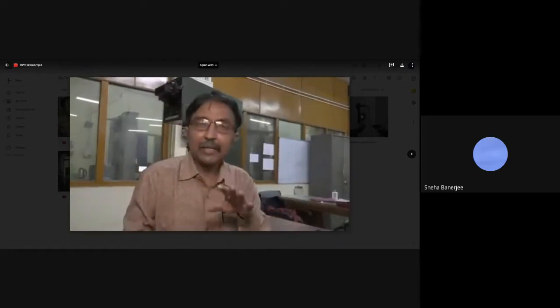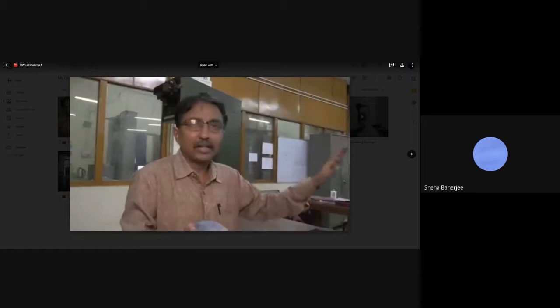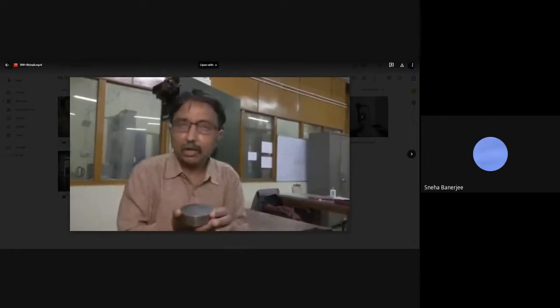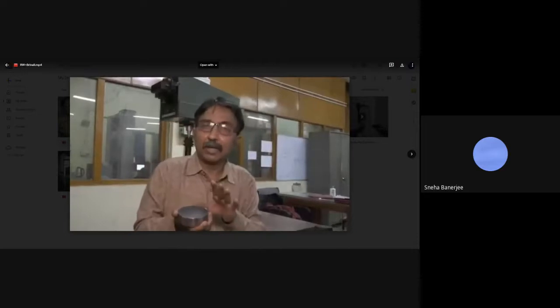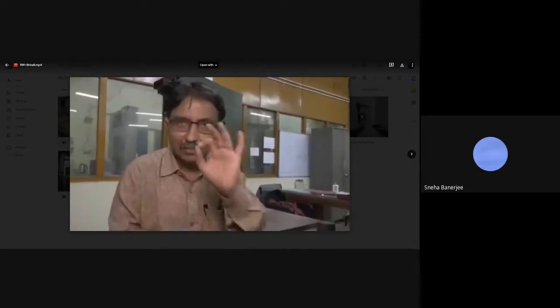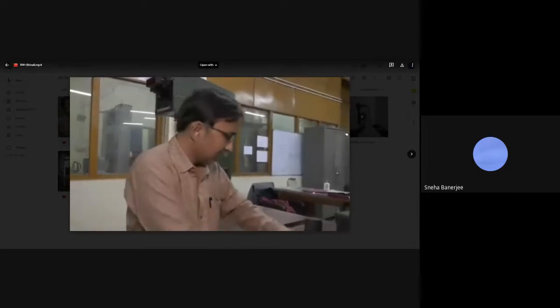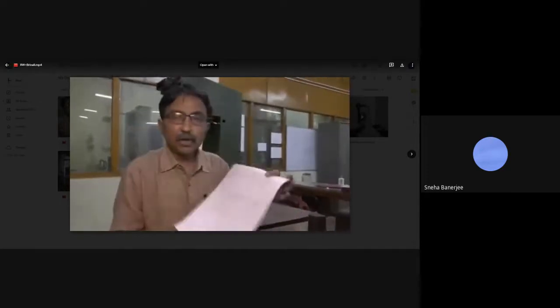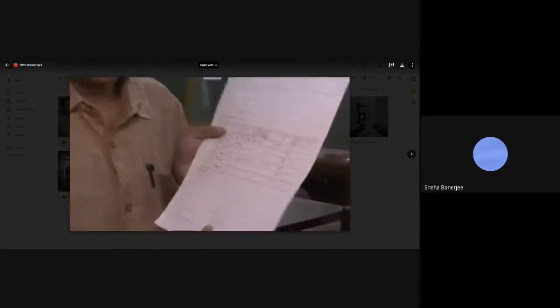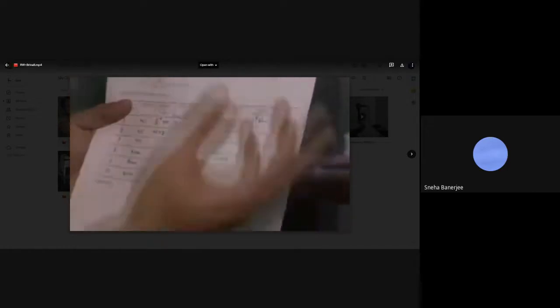We should keep in mind that inside the Rockwell hardness test, right now, though we don't have the provision to go for superficial Rockwell, there is a special type of Rockwell hardness test where we can go for superficial Rockwell hardness testing. The last point I want to mention is in the report. On the back side of the report, you will find a particular column where the Rockwell hardness number, whatever you have got from here, is to be converted to the Brinell hardness number. There is a column for that.